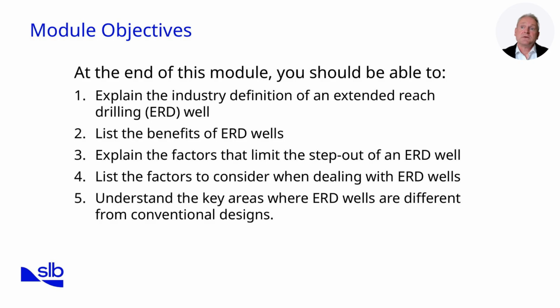In this module, we'll focus on the practical aspects of extended reach drilling. We begin by reviewing mud properties, where we'll see how rheology, fluid loss, and lubricity have a greater impact on hole cleaning and ECD management in long horizontals. Next, we move into drilling efficiency strategies and parameters, highlighting how flow rate, rotation, and disciplined cleanup practices shape performance.